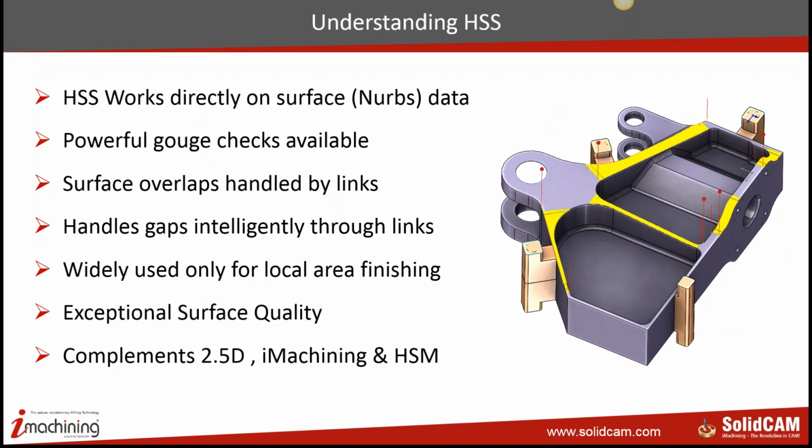It means that unlike HSM or HSR, we do not create any intermediate mesh or triangulation and machine the triangulation. What we do directly here is we pick up the surface as it is and machine the surface. It's either a single surface or a group of surfaces. So the first key thing here is it works directly on NURBS data.